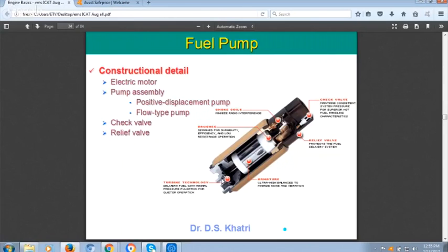Another problem we observe, many problems come from Bangalore. What is the problem? There, the people are mixing even water. Water content was very high in petrol. So the injector plunger got rusted and it is not moving, and the vehicle did not start. We cannot ask people not to mix water because you cannot control the 120 crore people, but you can control your technology.